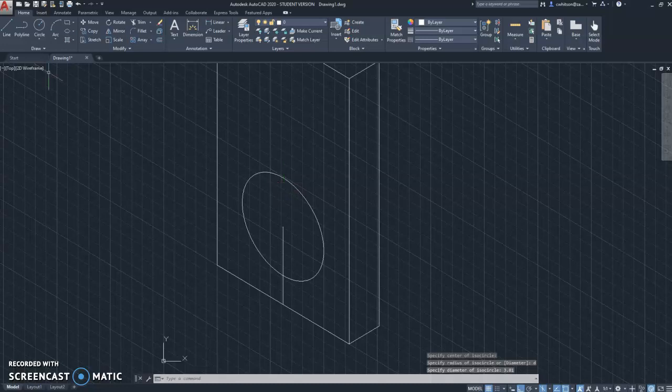And there's also an inner circle. Let's make that an ellipse, isocircle, that has a diameter of 1.524. All right, now for the thickness, these are going to create a bit of a cylinder.